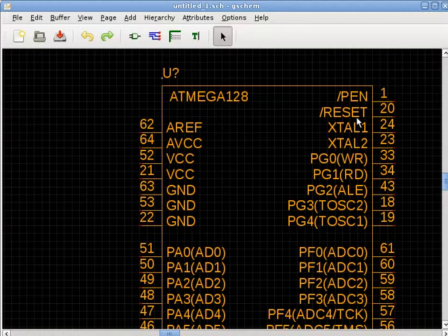When you see a slash in front of a symbol, it means the pin is using quote-unquote inverted logic, or active low logic. Most of the time, especially in software, we associate 1 as a high value and 0 as a low value. So when we look at a circuit diagram, we would also think that way. When I want to reset the board, I want the reset pin to experience a high voltage, and if I don't want to reset the board, I want it to be a low voltage. But in reality, it's exactly the opposite. This is called an active low type of signal, which means when the voltage is low, it is asserted, it is active. That's what the slash is for, indicating a pin is active low instead of active high.